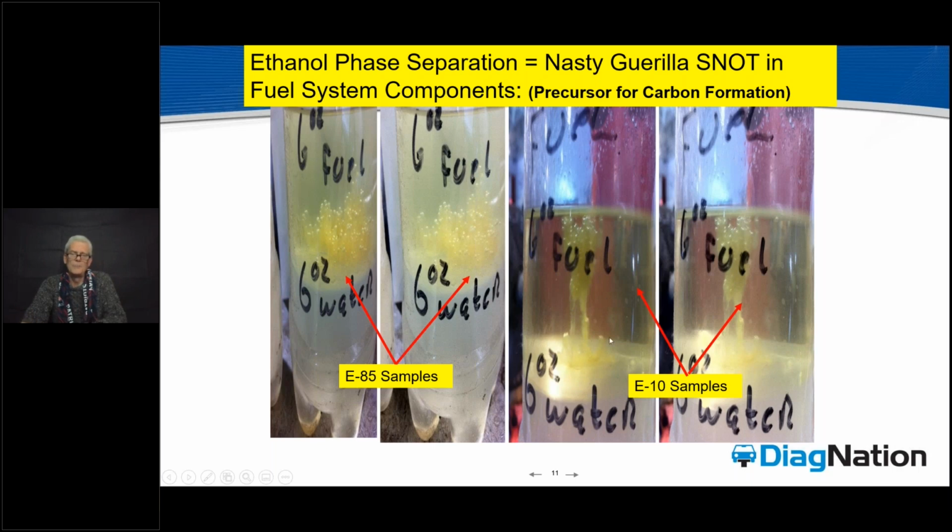This yellow substance with the little oxygen bubbles pulling up here toward the vapor space is the actual, what I jokingly call the gorilla snot, but that's the actual yellow paraffin wax that is oxidizing and being pulled out of the fuel. Now, what these oxygen bubbles are trying to do is get the deposit up here so that the oxygen bubbles can release into the vapor space.